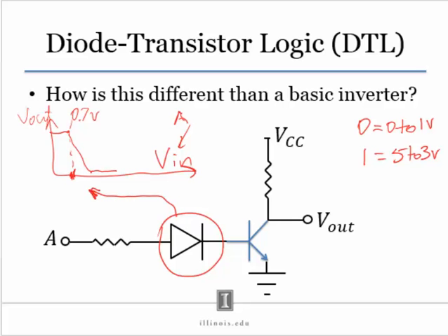essentially what it does is that it will add to this threshold here, right? And then with the diode here, we will not turn on until, can you think when? Okay, maybe you figured it out, 1.4 volts, right?